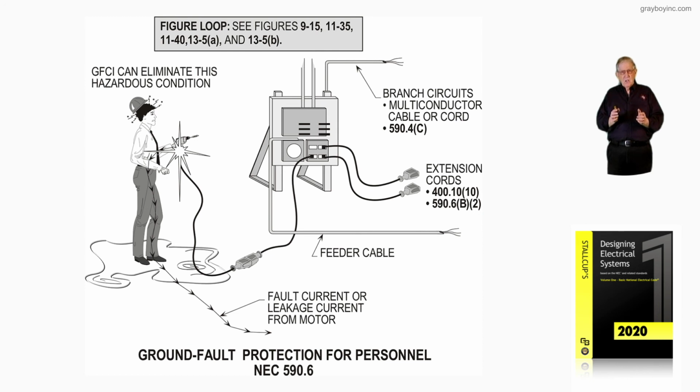I'm not saying that meets code now or meets the manufacturer's recommendation, either one. I'm not saying that. I'm just saying that sometimes they will make that rule because that means in some facilities, someone's just going around all the time checking GFCIs if there's a bunch of receptacles like that or breakers protecting receptacle outlets that are used by people. And then sometimes you have the portable GFCI.